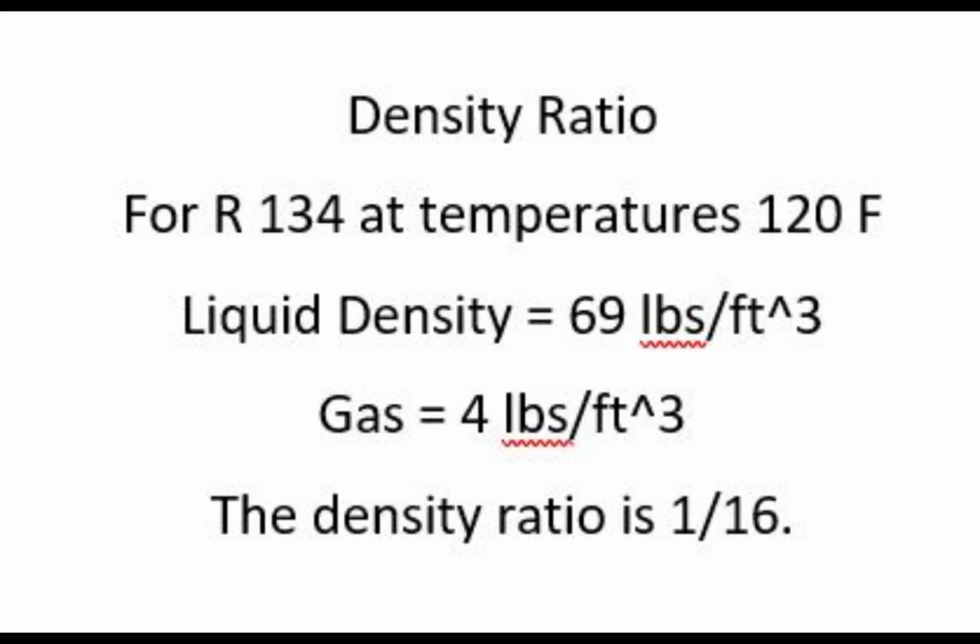And so we go to RefProp and we say, okay, the air is rejected outside at 120 degrees F. If you look at the density ratio between the liquid density and the gas, it's 1/16. All we have to do is be better than a quarter to be able to get enough electricity out of the system outside to cover all the electricity that we came in with from the grid. So it's possible that we can recover all the energy we reject outside.